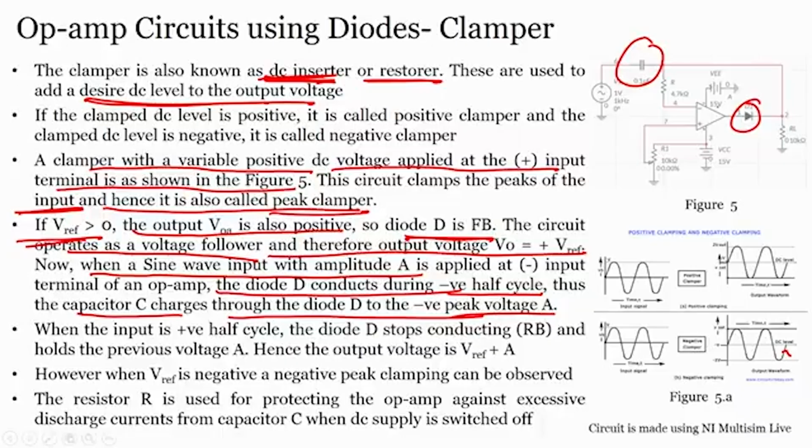So, I am assuming that when you know this, then we apply the peak signal, if the positive is not allowed, negative is allowed, right. That means in the negative cycle if the diode conducts, then only the capacitor can charge, otherwise it cannot charge. So, these are the prerequisites that you need to understand. I hope that now, at least now, you all know what is a capacitor, you all know what is a diode, because to understand complex circuits such as this, or at least a little bit complex circuits, you need to understand the basic components and the role and the application of basic components, or the working of the basic components.